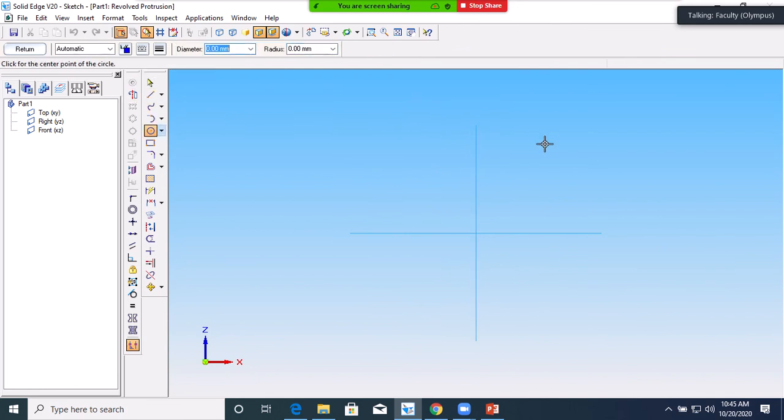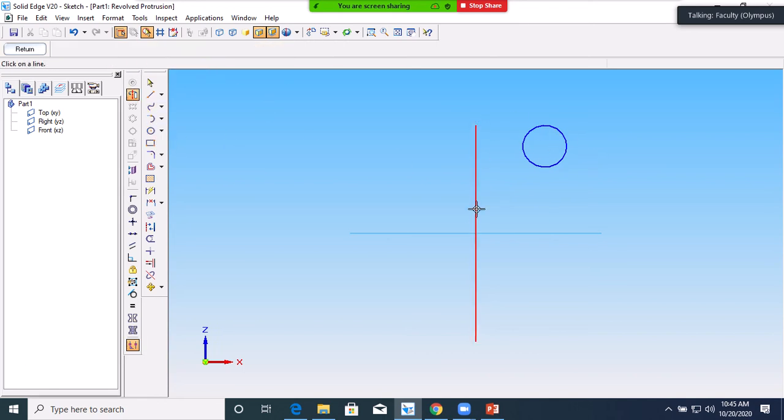Say I want a ring, a circular ring. So I created a profile, a circle shape profile. I will give the axis of rotation. This profile has to revolve around this axis. You can create the axis of rotation manually, or you can select this reference line. I will select this as the reference line, so this profile will turn around this one axis.